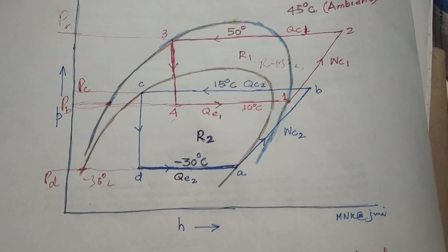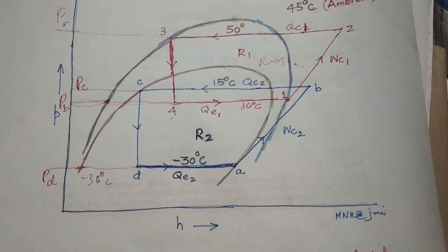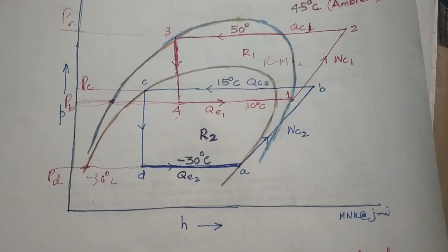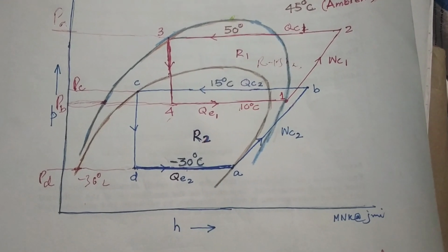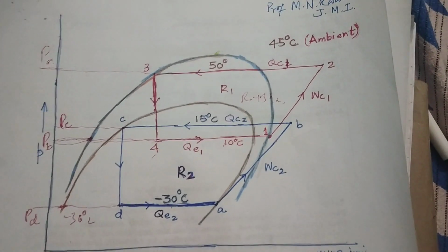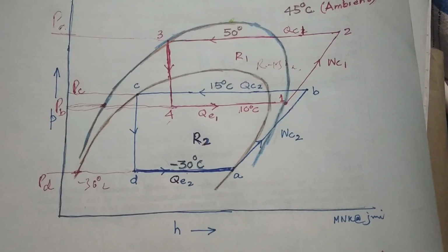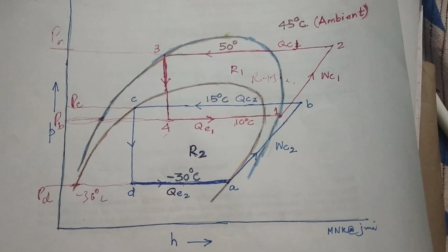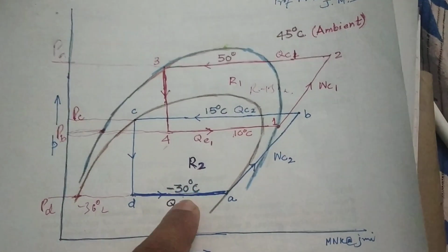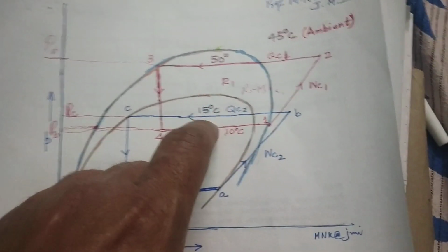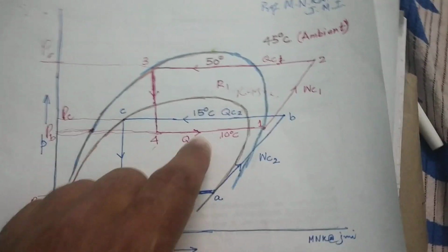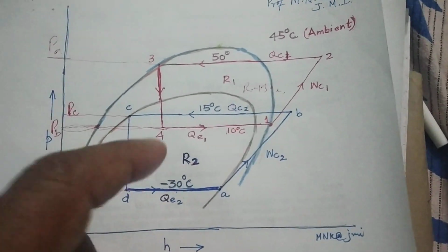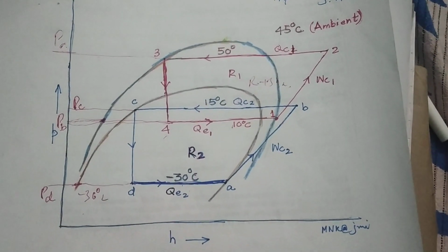A cascade refrigeration system is nothing but a combination of vapor compression systems, two or even three; here two is shown. Very low temperature refrigeration can be achieved at higher ambient temperatures, and therefore we have to select refrigerants which can serve low temperature applications and have critical temperature values which can solve this problem. We cannot choose this refrigerant or this refrigerant for one particular purpose. We cannot achieve it with the help of one refrigerant.